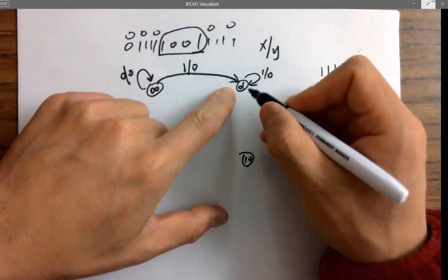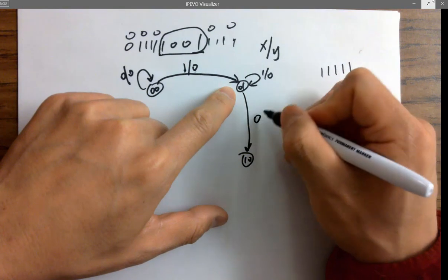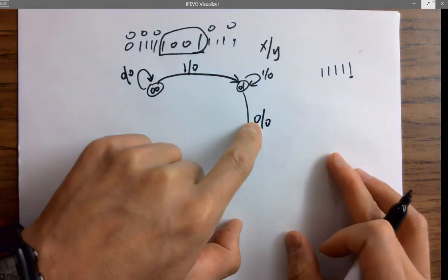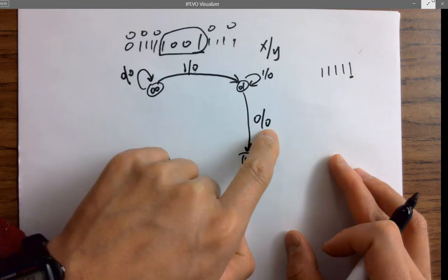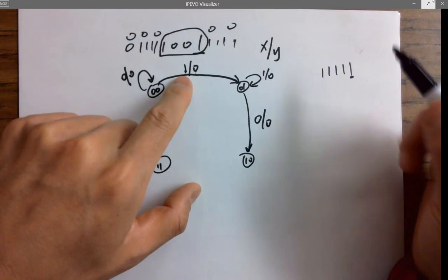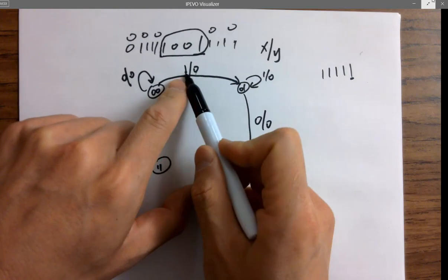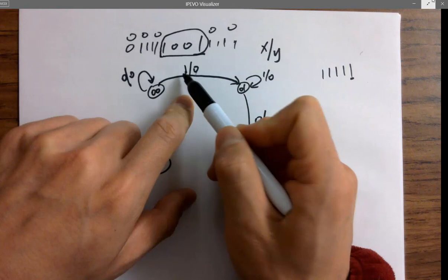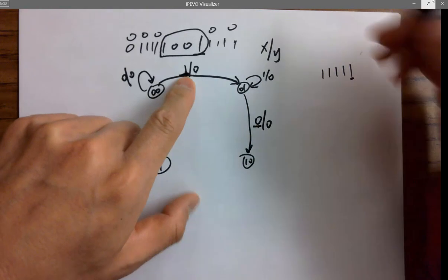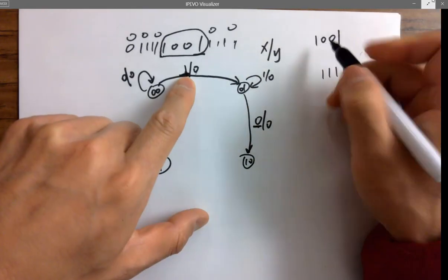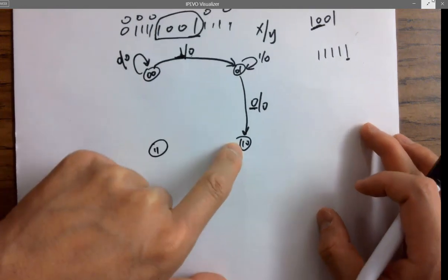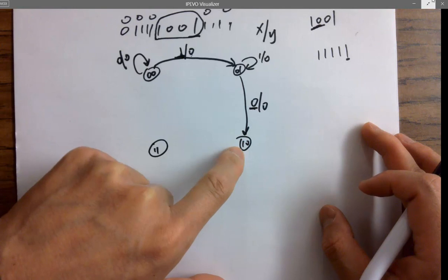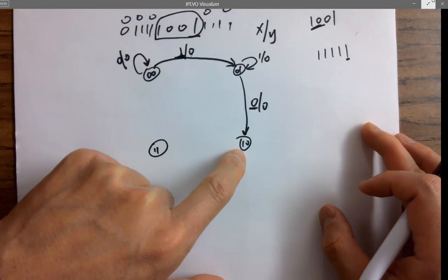Okay, we just said if you have a 0, you move to the next. So you have an input of 0, and output is 0 as well because it's not finishing the sequence yet. So we can see the input right now we have 1 and 0. Okay, so these are the 2 inputs, 1 and 0. Since we want to finish 1, 0, 0, 1, now we are here. So we move to the next state. You are waiting for another 0.